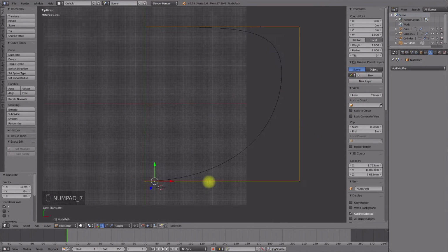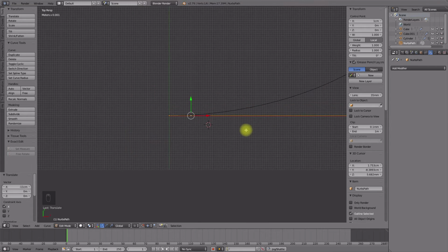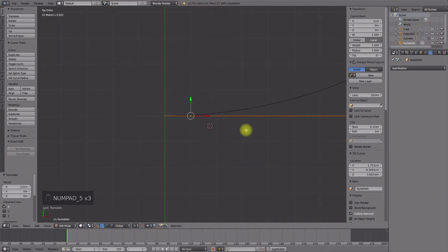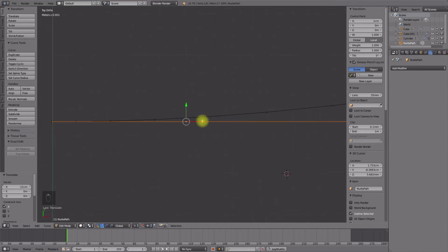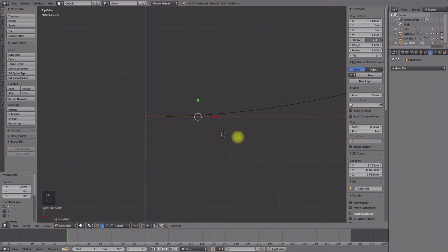Or better, activate the snap to grid function with increment snapping. Make sure you are in the top level view and orthogonal perspective. Using the grid, you can model the path very fast and precisely. Zoom in to use the subgrid level to model with more precision.